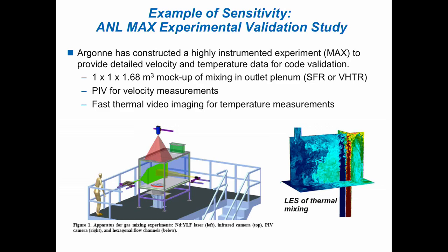It turns out that the RANS codes can run somewhere between 10,000 and 100,000 times faster for this particular problem. And one of the main reasons is that when we simulate it, we're simulating it in an unsteady way. The first thing you have to do is fill up the box with turbulence. So if you have a tiny straw in a really big room, you're going to be waiting for quite a while. And experimentalists can always defeat CFDers just by making their box bigger.